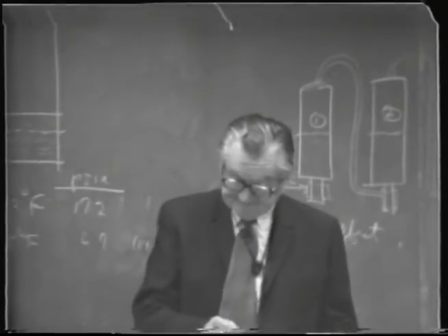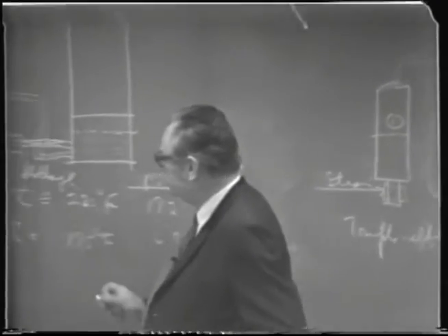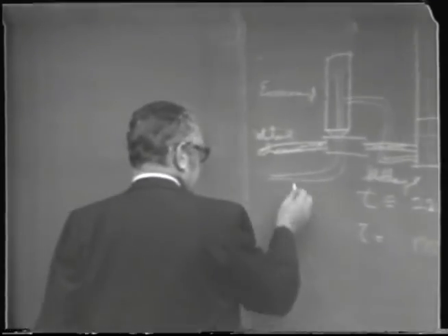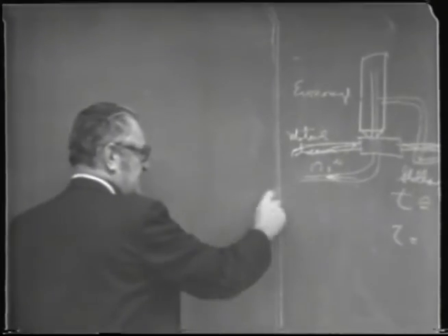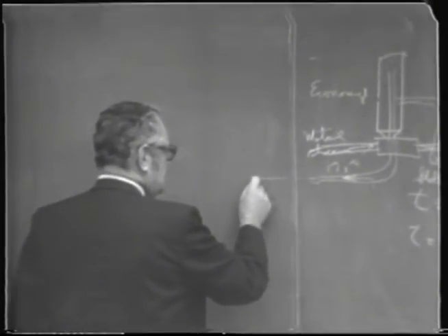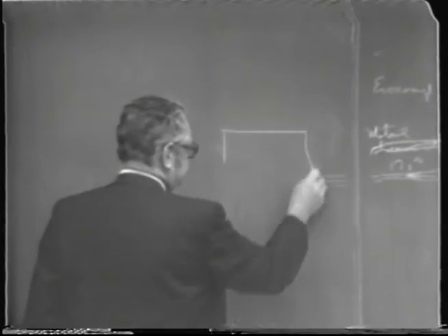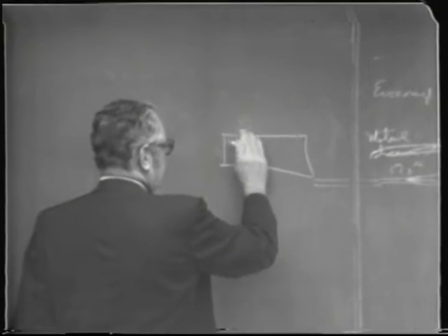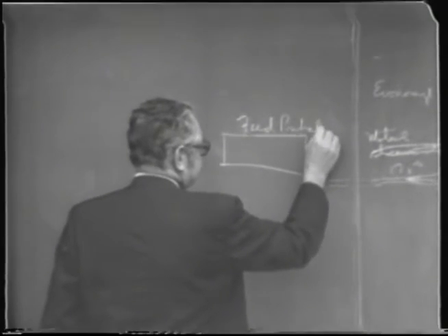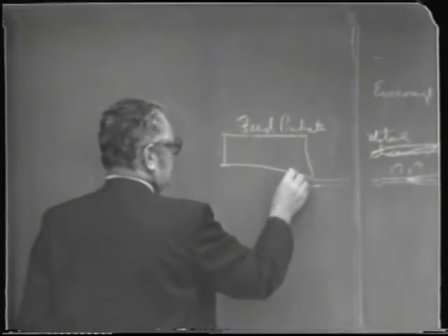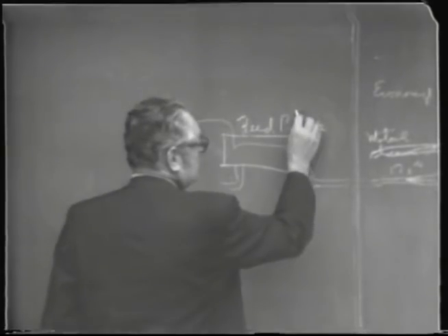So consider also that this stillage going out, if we want to say 175 degrees here, leaving the economizer, is still going to be utilized in a conventional type heat exchanger for feed preheater. I won't show the feed preheater.